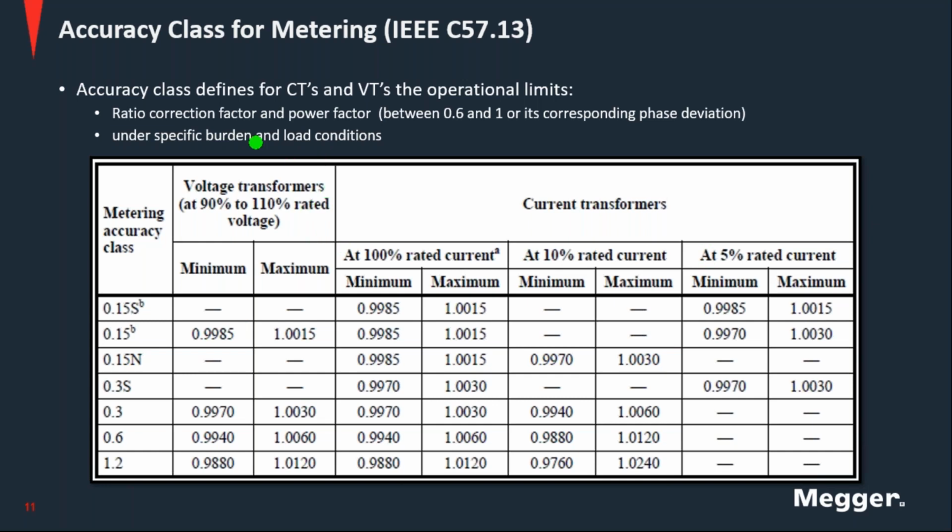this also depends on what is connected to that instrument transformer. So these instrument transformers do not deliver power, but they definitely have a load connected to them. They have a circuit that is basically composed of the wiring and the metering and control devices.